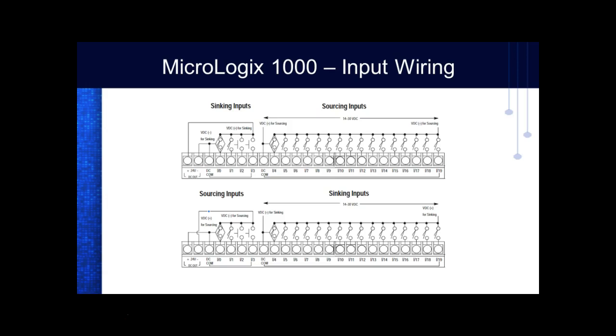So here's the common right here, right? You understand? This is going to all my inputs. So I'm jumping these wires down. I'm sorry. This is out on my actual physical devices themselves. And then what do on the DC common? They've got this hooked up to what? Plus. You see that? So they've got this set up for what? Sourcing inputs. They've got this one set up for sinking. That makes sense? And then down here, they've got them swapped around.